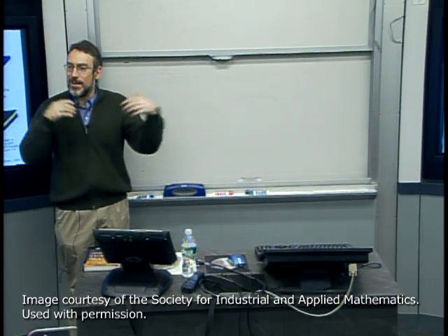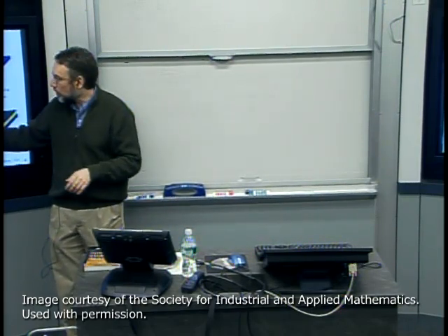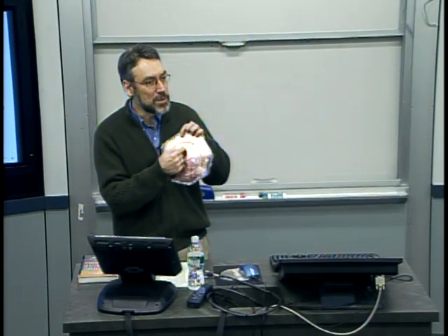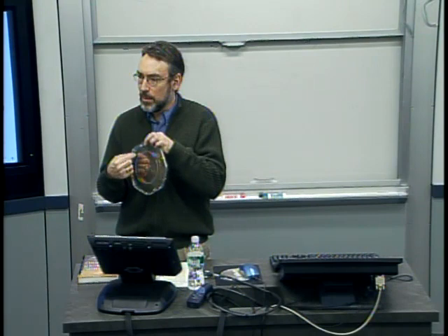There's also exquisite environmental control in the equipment that's used for this. Imagine that I don't need to line up just for one transistor. I got to make sure across maybe a 1 centimeter squared or 2 centimeter squared chip that all of my transistors are lining up. And in fact, in older technologies, I had to make sure the whole wafer was lined up because I had a big glass plate that I was using in almost a 1-for-1 transformation. So everything across the whole wafer had to be lined up.